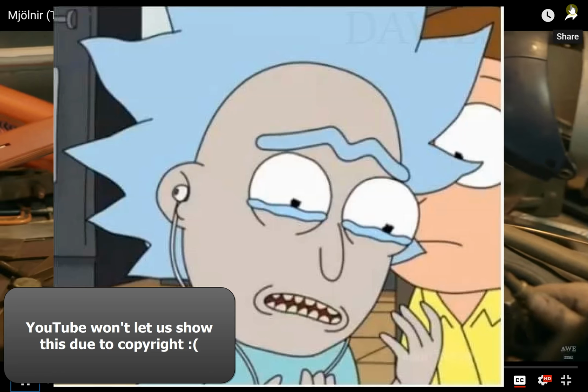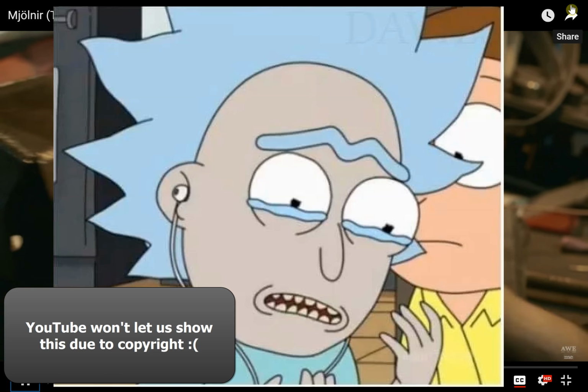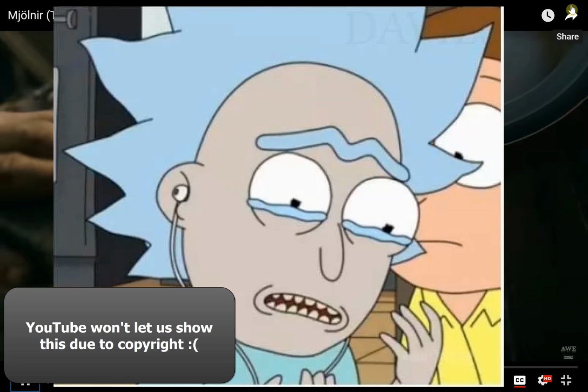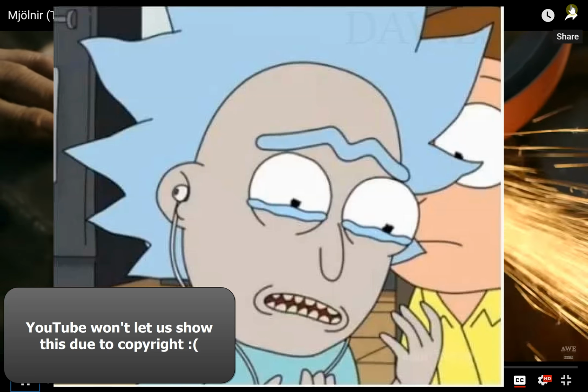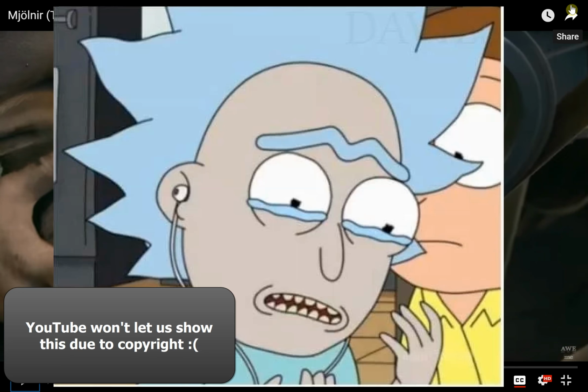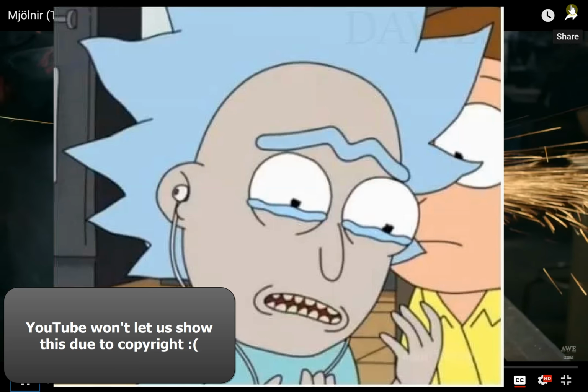So they're welding these different pieces together, okay? The end pieces were still sticking out, so again, they locally heat those up and bang on them, and then they weld them shut. And now you've got something that looks more or less like the hammer, okay? They're grinding away the excess from the welds, because again, welding is just melting. And so there's this pool of metal. It's tough to get it really fine, so you often do some cleanup afterwards. You clean off that extra pool of metal there. They're starting to polish a little bit, getting it pretty clean.